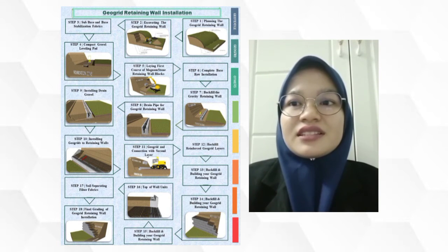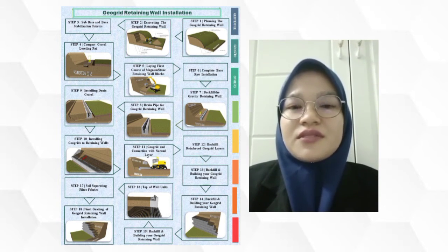Ensure that final grading is done on the top and bottom of the retaining wall. Make sure to protect newly placed planting soil from erosion during heavy rain or surface runoff.